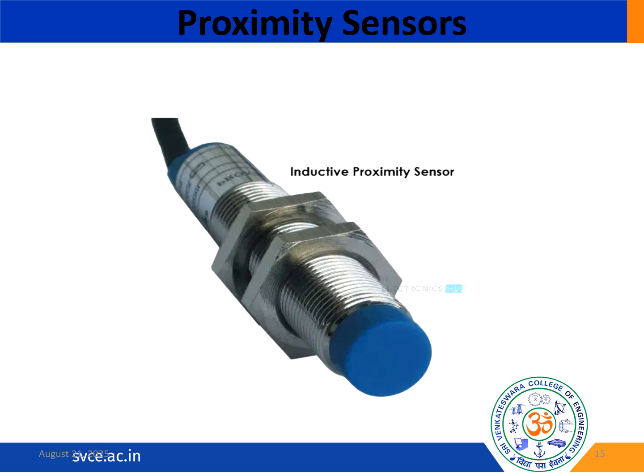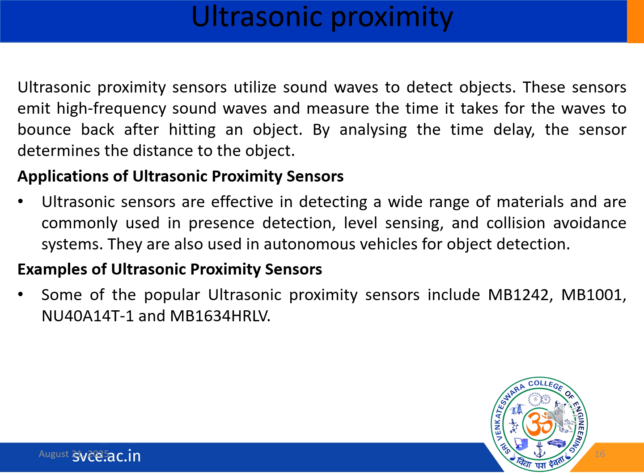When you consider proximity sensors, they use an electromagnetic field. The target object is a metal which enters the field and induces eddy currents. These currents alter the field and it triggers a change in the output. So this is the main function of a proximity sensor.